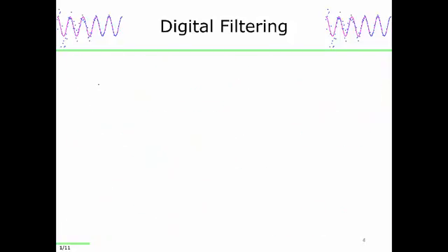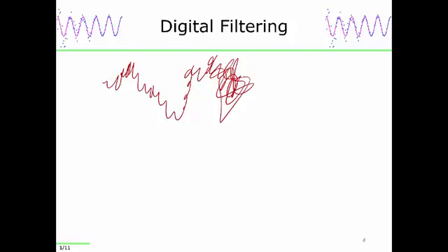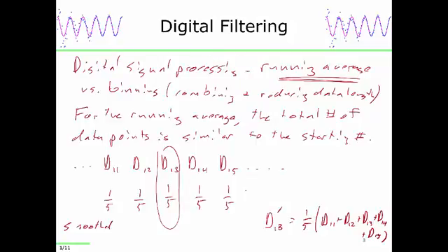So if we think of the data, something that goes in time, what we're doing is building our little digital filter and convolving it with the data trace. Because what are you doing in a convolution? Well, you're taking the filter and you're sliding it across. You're taking one function and you're sliding it across the other function, right? And you're integrating over that value as you slide. Well, that integration numerically corresponds to summation for discrete values. So the summation is equivalent to the integration that we consider when we do convolution.